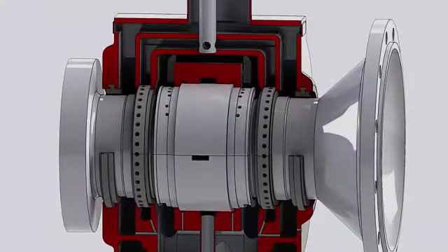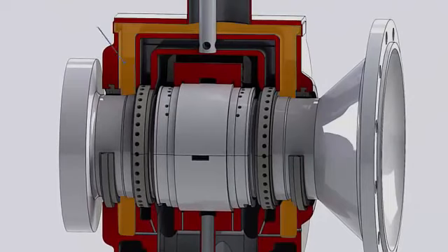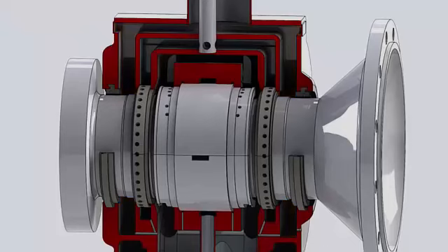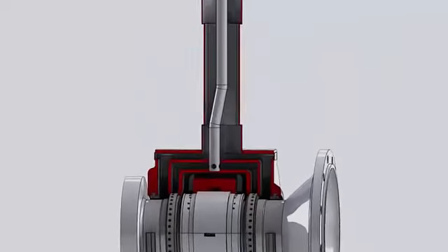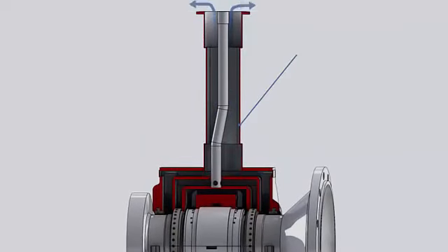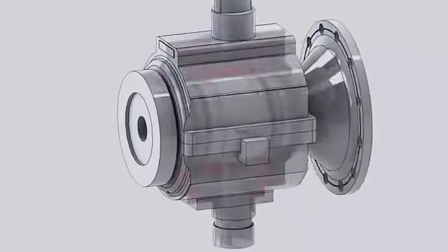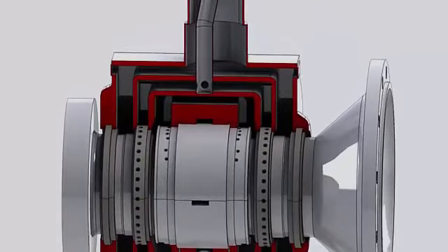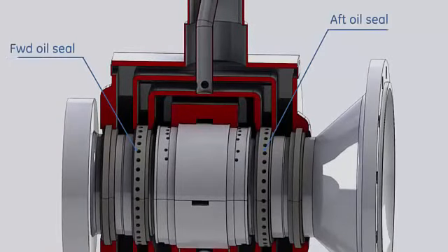Bearing 2 has a vented cavity. The compressed air leaking from the outer labyrinth seals is vented to the atmosphere through a vent pipe mounted on the top of the housing. Inboard of the outer air seals, 2 pressurized labyrinth seals are located for lubricant control.